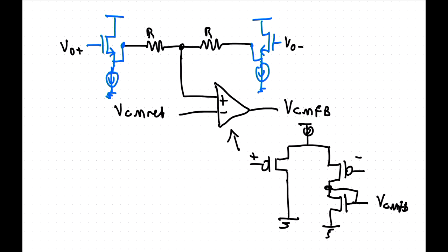Okay, common mode, fully differential. I think that is it. Yeah, I should probably say that when you read papers, sometimes you see that they have shown a circuit diagram, and then in some line someone says, "Oh, by the way, this is actually implemented fully differential on the chip," and they just leave it like that. So you might not see that they do it fully differential, even if they do. It's left as an exercise for the reader to transform it into a fully differential circuit.